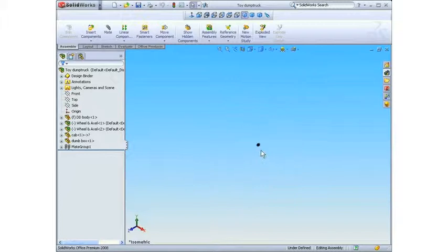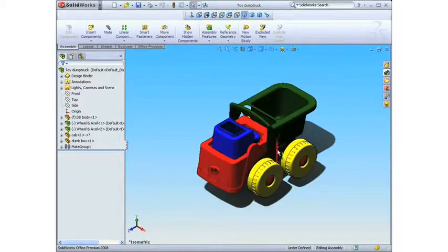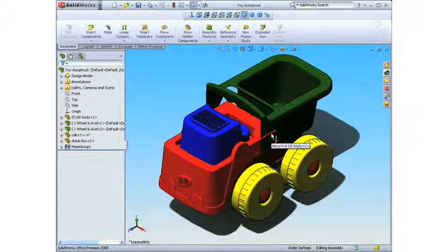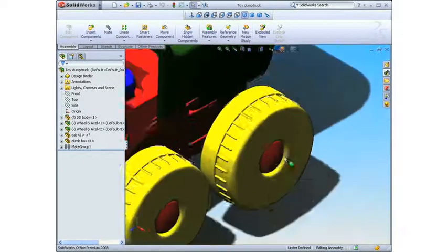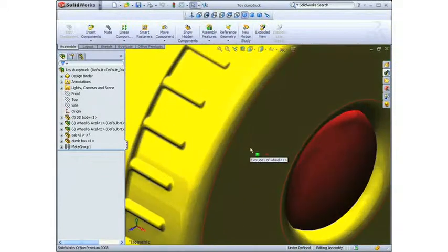Again, let's zoom our model too far out, and again, select the fit command, this time pressing the F on the keyboard. So we'll see both those methods are methods of zooming to fit. Now at times you'll know that there's an exact area you want to zoom into. One way is to hold the cursor over that. We're using what we call dynamic zoom.